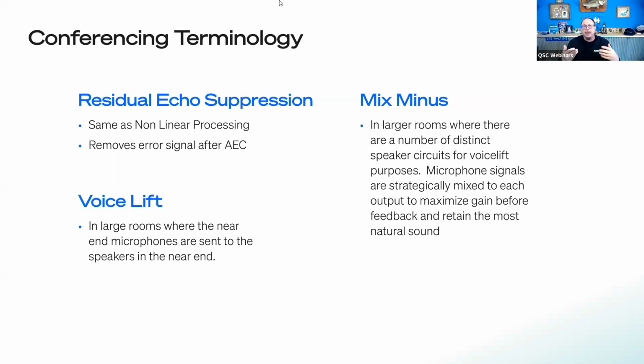You have to explain to them. They're like, well, I don't hear it back here. And it's like, no, it should just feel really natural when it comes out of there. Some people will be like, I don't think that the mic's working because I don't hear myself in the room. And if I'm 20 feet away from the loudspeakers, the people under it should hear my voice naturally. And the person at the front of the room shouldn't hear their voice. So I could do a 2 hour thing just on voice lift.